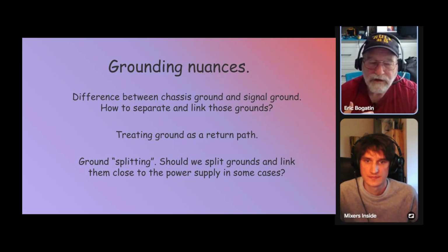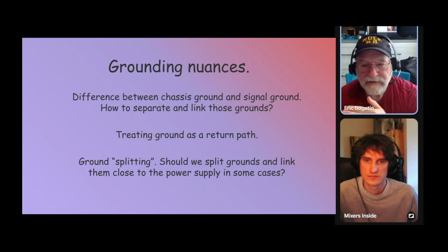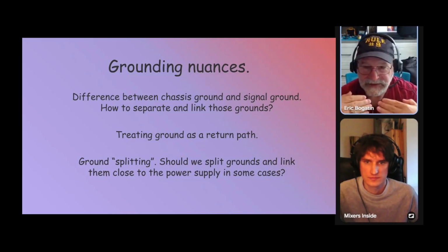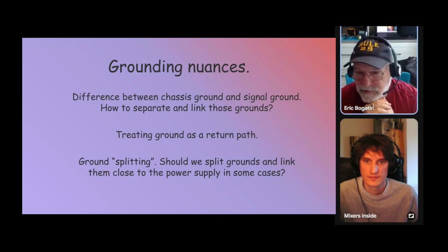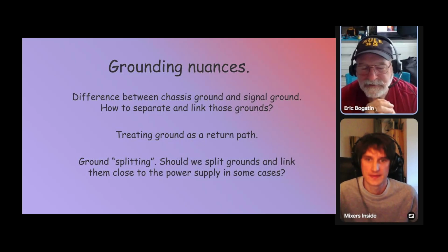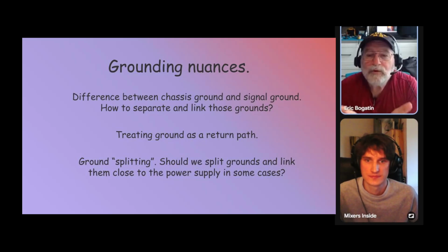The danger you run is if you're not really careful in how you lay out the signals, so that your digital signals and even some of the analog signals don't cross that ground plane. If any of those signals cross the split in the ground plane, you can dramatically increase the crosstalk that you see. So it's a risk-reward ratio.